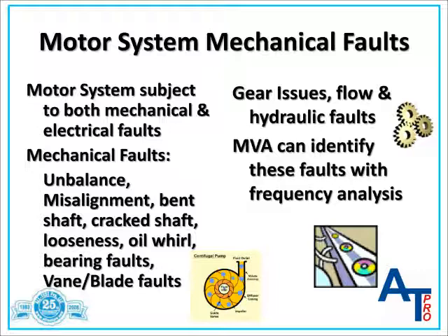These hydraulic or mechanical faults create forces which are applied from the shaft to the bearing and bearing support. These forces cause the bearing housing to periodically move at the frequency of the applied force. The amount of the motion depends upon the strength of the applied force as well as the mass and stiffness of the structure. Because of this limitation, early indications of many faults remain undetected, and several measurements are required at different locations on the motor system, usually at the bearings, to identify developing faults using vibration analysis.